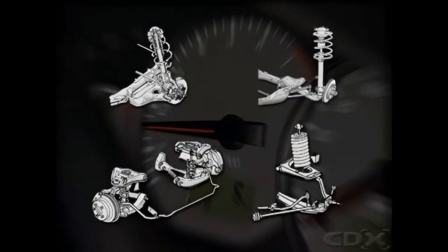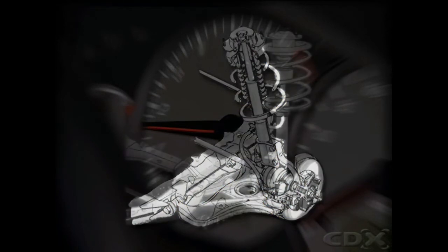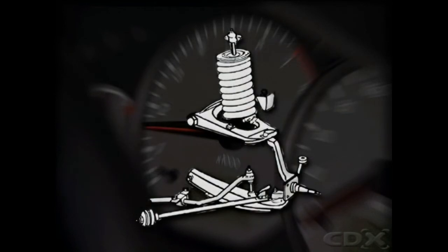A number of different layouts are used in front suspension systems, incorporating either a driven or live axle or a non-driven or dead axle. This independent driven or live axle front suspension arrangement consists of coil spring, lower wishbone and McPherson strut. This arrangement consists of coil spring, strut, tension rod and lower control arm. This non-driven or dead axle front suspension arrangement consists of coil springs, lower wishbone and upper wishbone. This arrangement consists of coil springs, tension rod, lower control arm and upper wishbone.